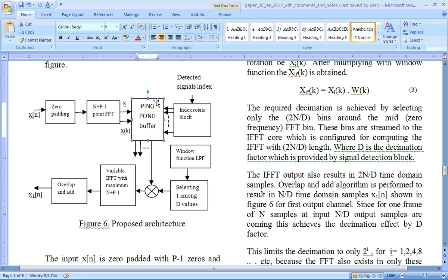You got it? So how much does this assumption hold good? In ASIC, it holds very well, because normally 5 read ports or 6 read ports is a very common thing. But in FPGAs, you have only 1 or 2 read ports in block RAMs. Other than block RAMs, you can also implement your own memory with multiple read ports using slice logic, but that also takes a lot of area.